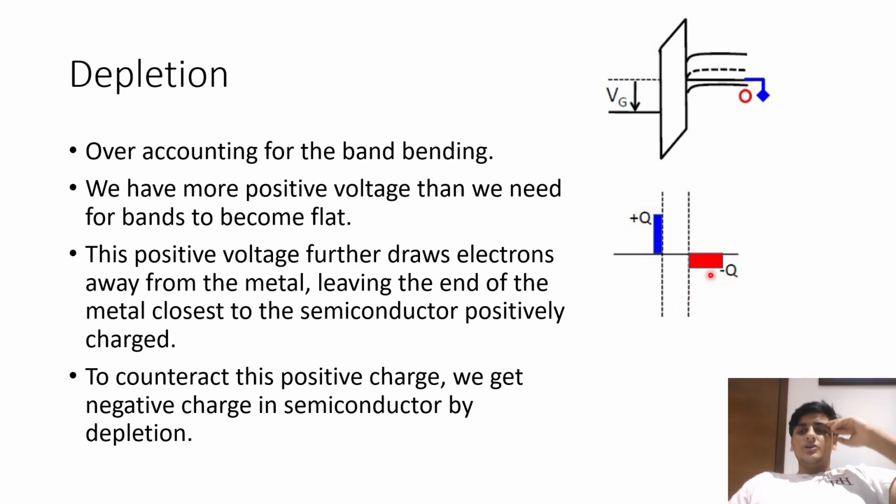P-type semiconductor. So when it repels holes away, it's not able to create a concentrated surface charge and balance this positive charge this way. It repels holes away, and as you know, the P-type semiconductor is going to have these negatively charged ions. So when the holes get repelled, those ions get exposed, and this entire region gets depleted of positive charge, and you have these negative charge ions remaining. The depletion region will last for as long as this negative charge perfectly balances out this positive charge.